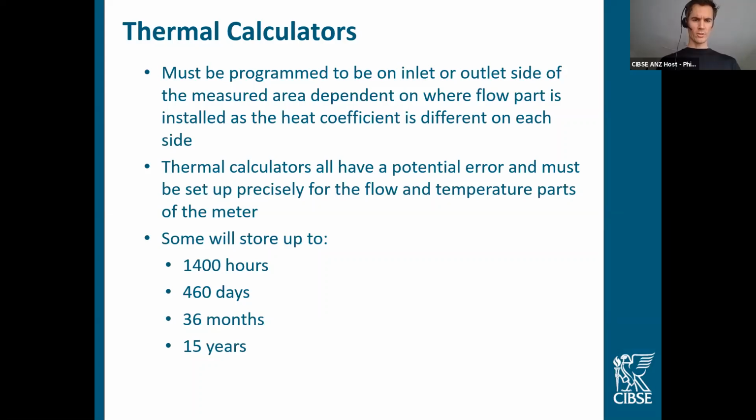So despite that, just to add to that question, just for my own edification, the K factor doesn't sound like it's solely dependent on the temperature, if you still need to be specific about whether or not it's on the inlet or the outlet side? So no, the K factor is solely based on the temperature, but it's based on the temperature at the flow sensor point. It's all programmed into the meter, but it should be using the temperature at the flow sensor point.